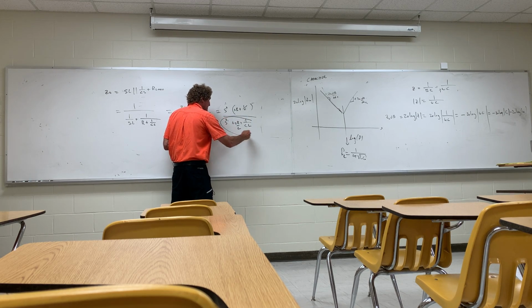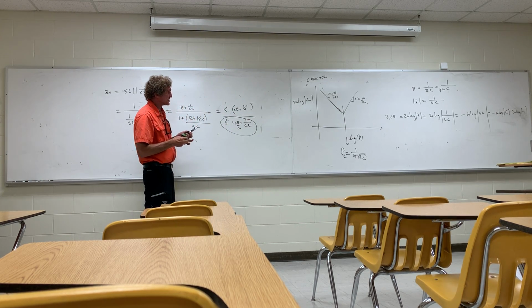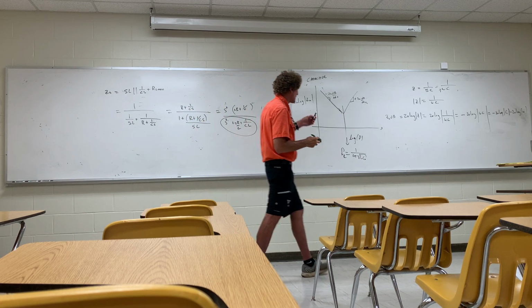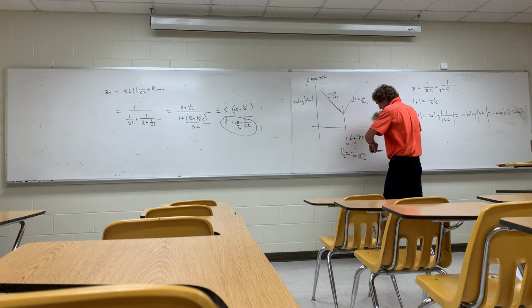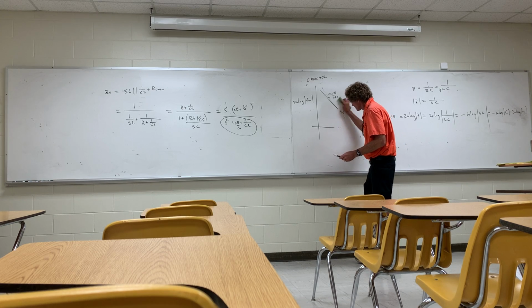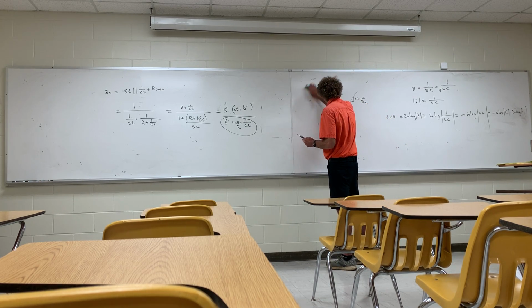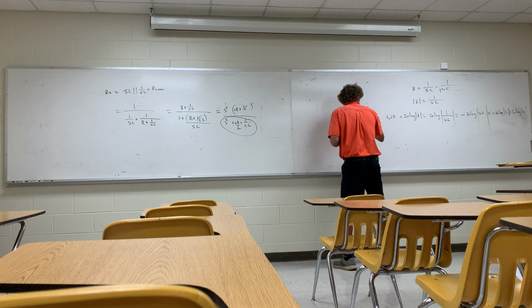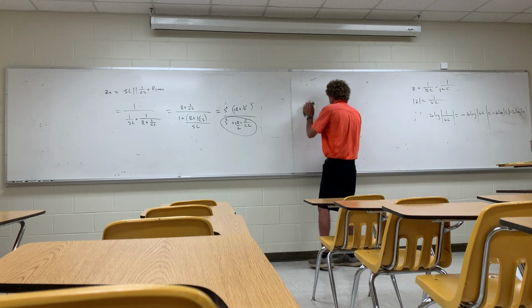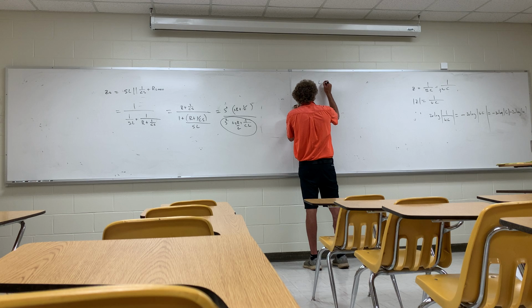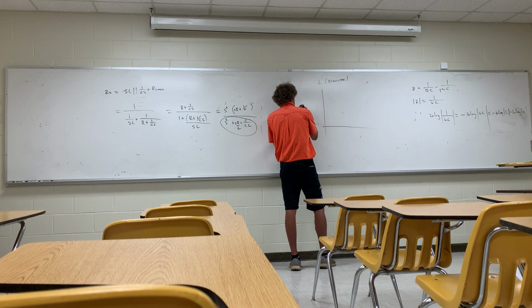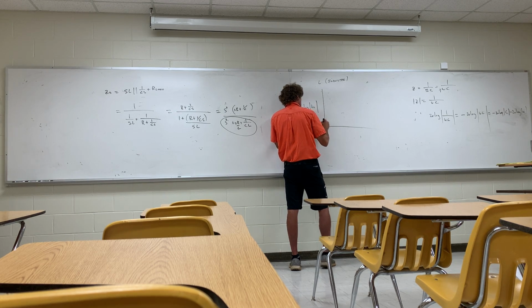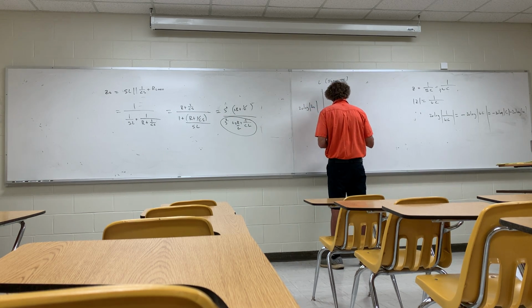Now, the roots of that are where the poles exist. I'm going to grab the actual plot of this and give you a clue. This is in his book, but for an inductor, the Bode plot of 20 times the log of the impedance of the inductor versus F looks like this.